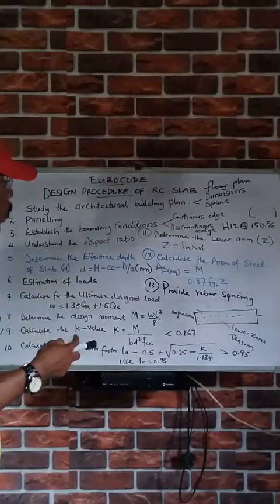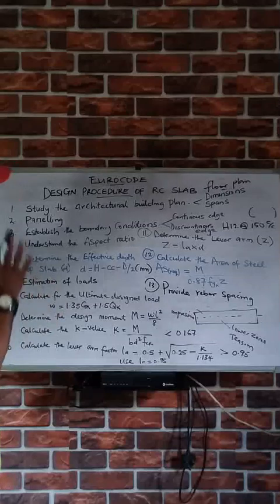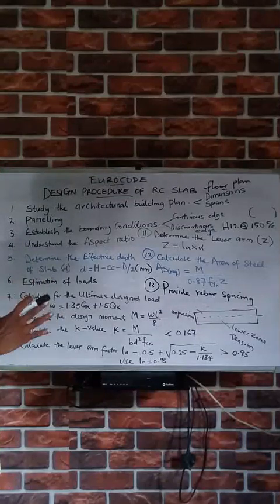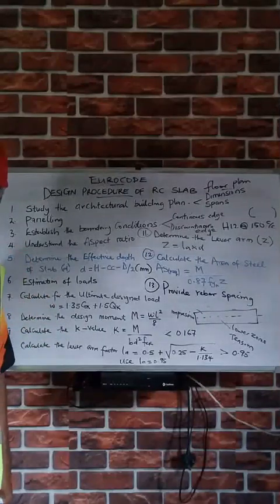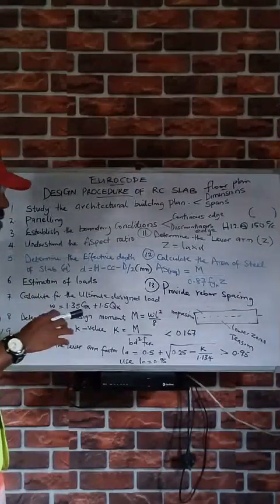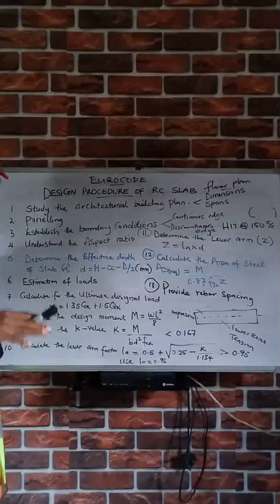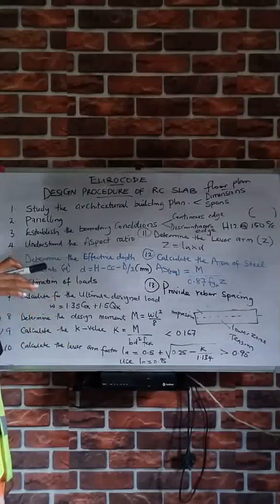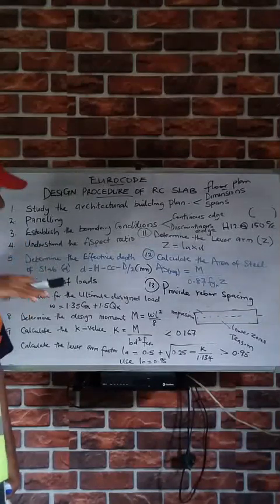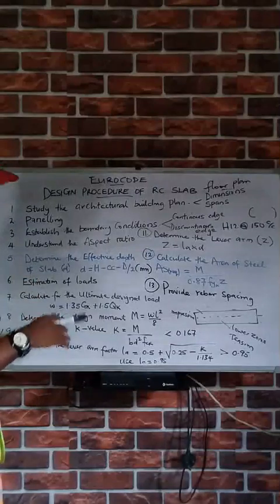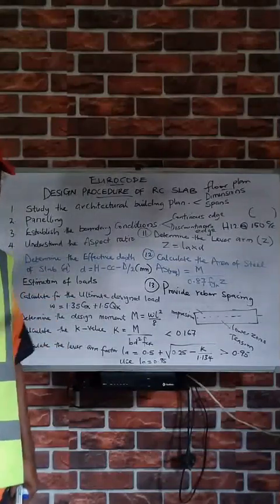Okay, so understand that this is just the steps that we need to follow. Then there are some cases where you might have different loading conditions. Okay, in terms of the ultimate design load, you see the variation. All right, so you have to treat those panels based on those variations. Okay, but if there are no variations, this ultimate design load is applicable because it's per meter run.